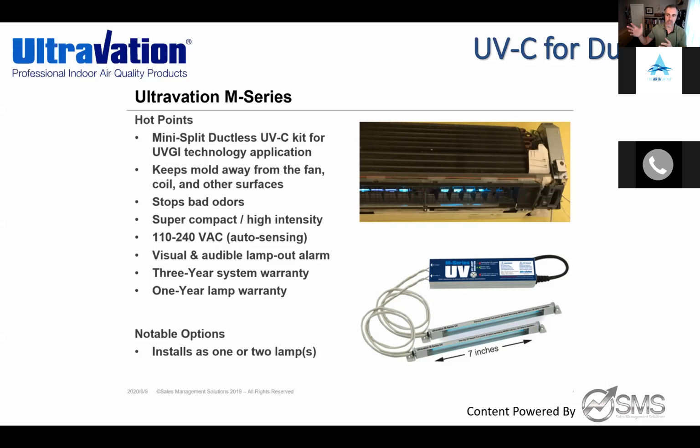A lot of companies are still promoting LED or little ionization strips, but that's only treating the airstream for the ductless head. I was like, you've got to look inside the unit. Your petri dish effect is where that coil is and where all the particulates are falling onto the coil surface area. If you still want to throw that in the airstream, great, but don't forget the inside of that ductless head, because I've torn them apart and those things get funky.